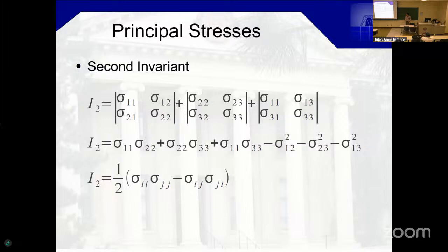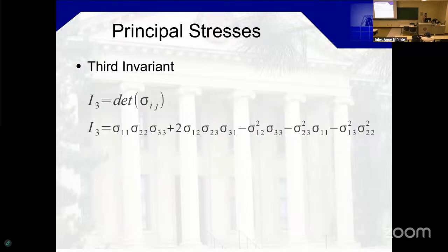What will I3 be based on this? It's the determinant of the whole thing. So you do the determinant of the one by one matrix containing each of the terms in the diagonal, then you expand to a 2 by 2 and find the sum again, like you did for I1. And I3 is the same, except you only have one matrix that's 3 by 3. So that's basically how you find your stress invariants.